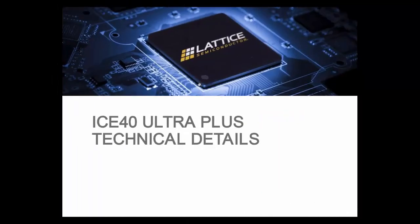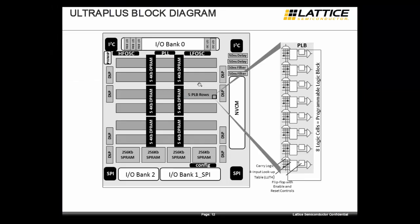So the technical details of iCE40 Ultra Plus family are as follows. The block diagram shows all the major components of the device. As far as the logic is concerned, we do have a 4-input lookup table logic block. 8 of these comprise a logic cell, where we call the programmable logic block, PLB. And there is carry logic in between each one, and a flip-flop per lookup table is available with enable and reset controls.